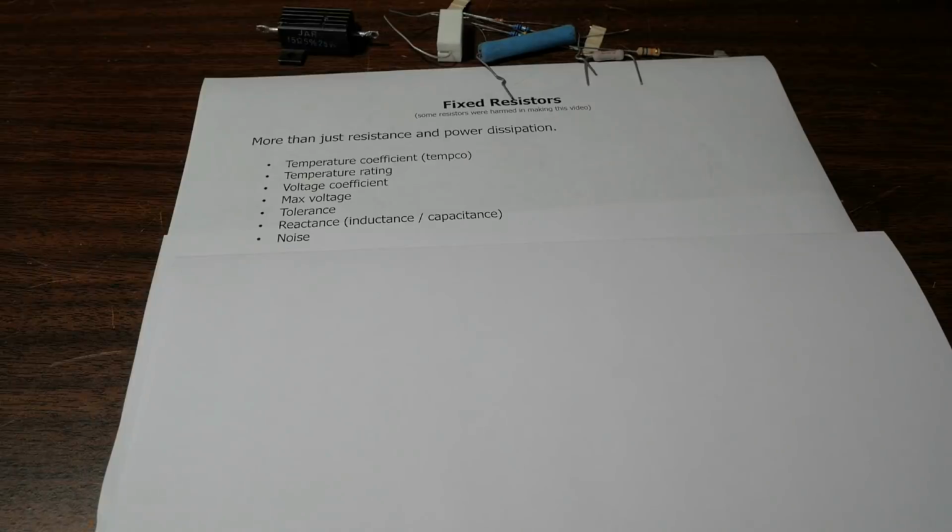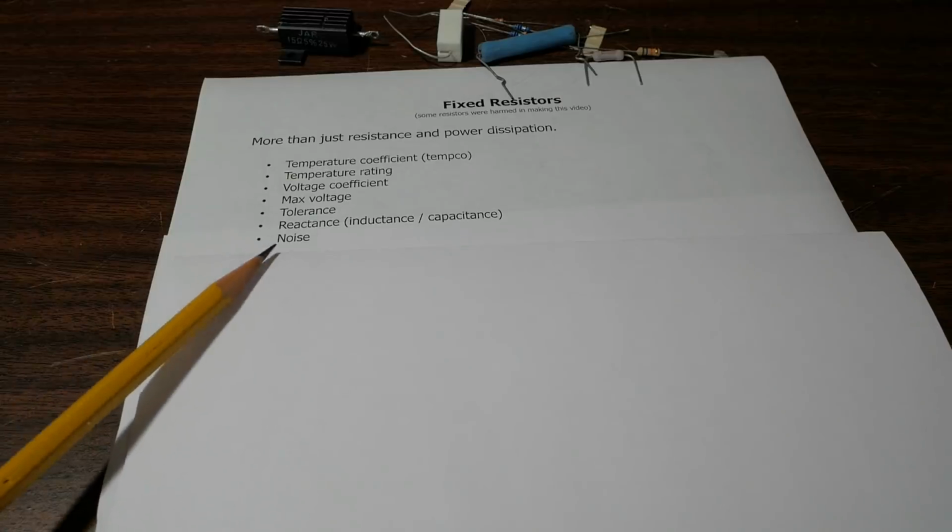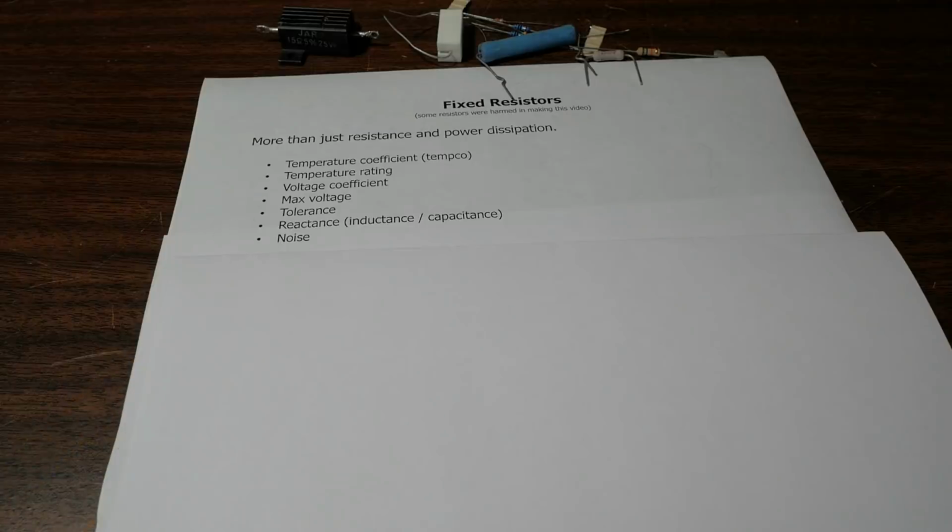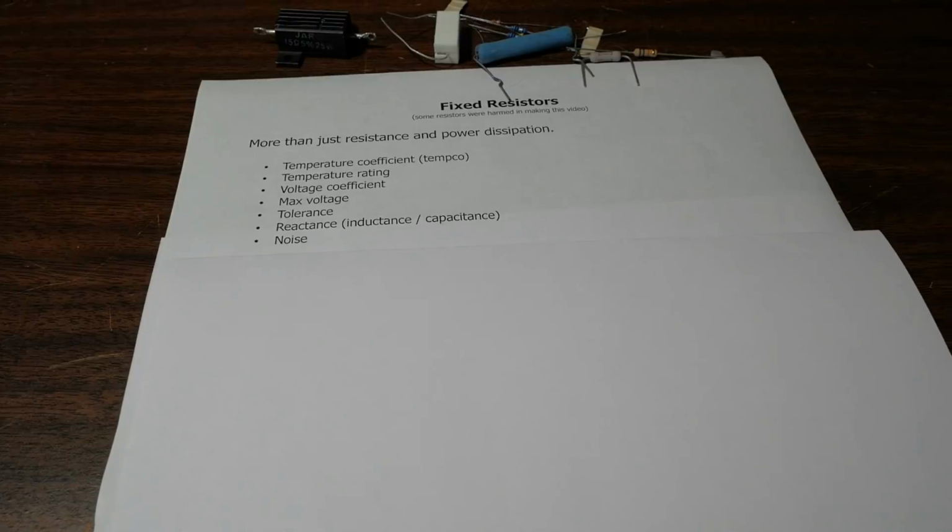In a high gain amplifier circuit, you want to minimize the noise as much as possible, so you want to select a resistor that has the least amount of noise. Noise can also be a problem in higher value resistors, so in certain amplifier circuits you want to have as high an impedance as possible within the circuit, but you're limited by the noise that could be produced in the resistors of higher values, so you have to choose a lower value.